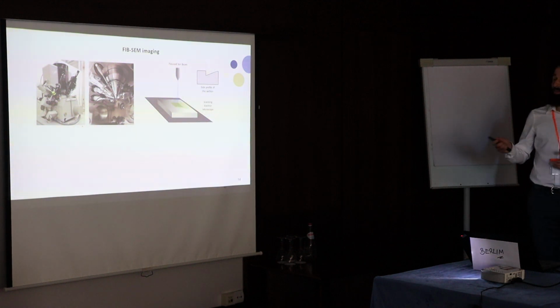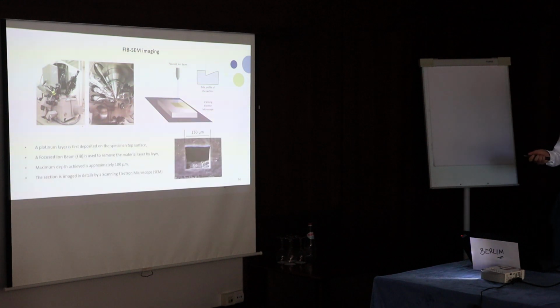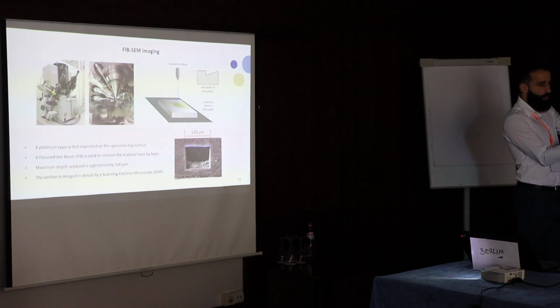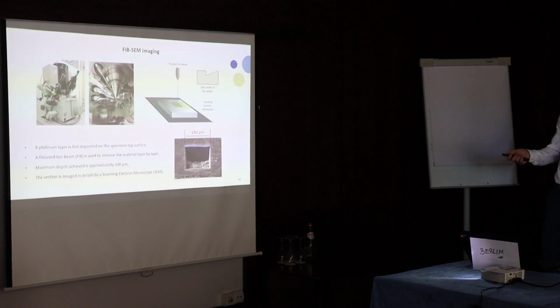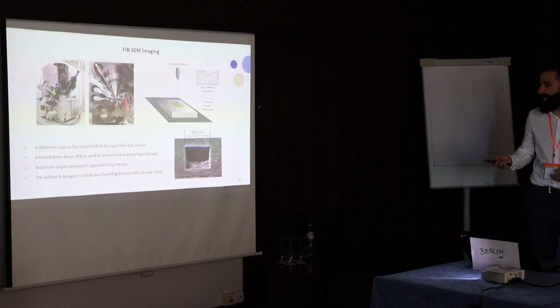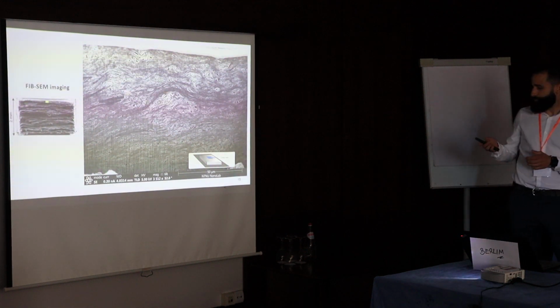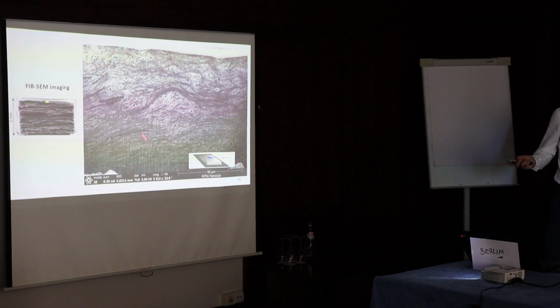We did SEM imaging. Basically, we drilled a hole on the top surface of the material and cut a section perpendicular to the plane of the sheet. The section was big, roughly 150 microns by 100 microns in depth. And finally, we got the first accurate description of how the material is made.